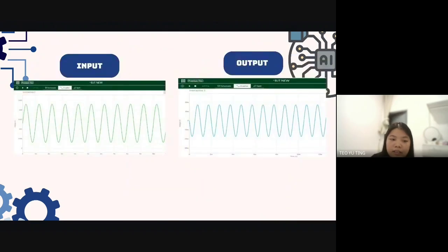Next. Finally, we use Multisim with a 10 millivolt, 1 kHz sine wave input. The simulation showed that the output signal was amplified and inverted. Therefore, the calculation and simulation both confirm that the common emitter amplifier works.